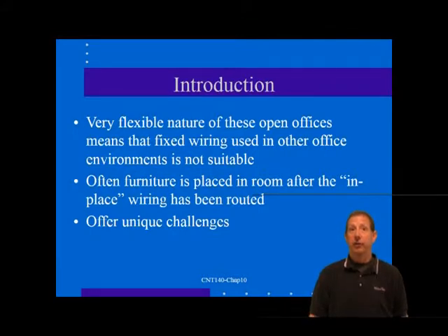Placing ladders to install standard horizontal runs is difficult, even if the cable has been pre-pulled to the expected area of the power communications riser. Now, if pre-pulled, enough wire must be left coiled in the ceiling to run down later through the pole and through the wire pathway to an outlet connector. This leads to wasted wire in the best case, and insufficient wire in the worst case.